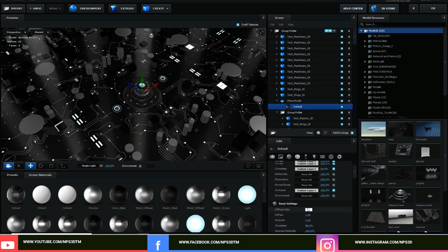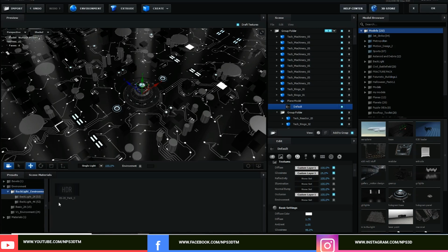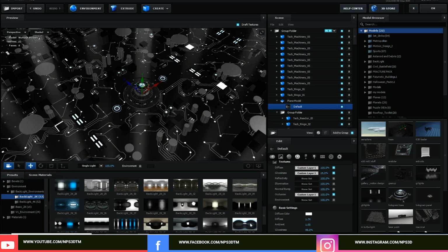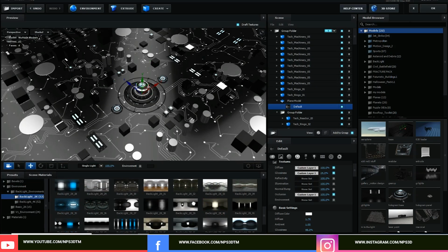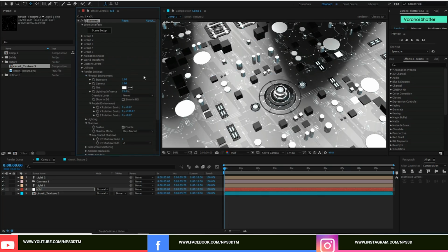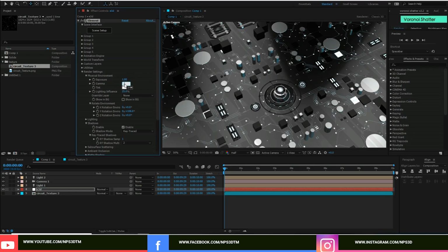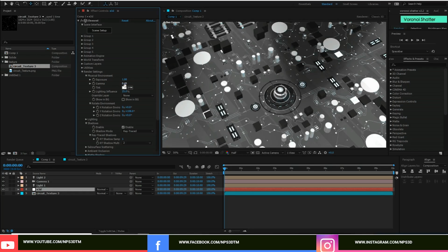And increase the diffuse color a little bit more, and change the environment layer again. Let's go with this one. So go to the lighting, physical exposure, and put 1. And the gamma I'm going to put 0.4, not 0.4, 1.5.